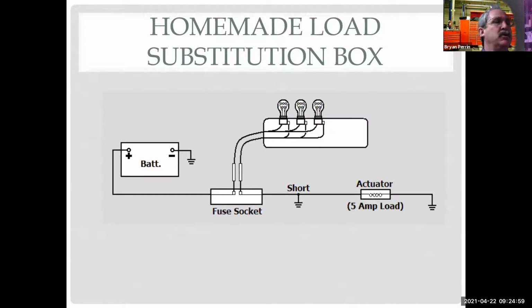So it comes down to how long it takes to find it. And the other thing is, I don't really know when I've found it. I don't know if I've got an intermittent problem. If I've wiggled the wire and made a change, I'm not going to know that using that resettable circuit breaker the way the book talks about. With this right here, I know instantly.